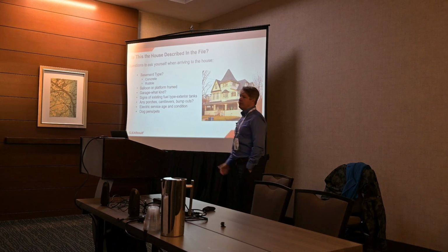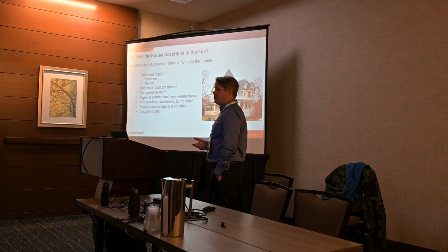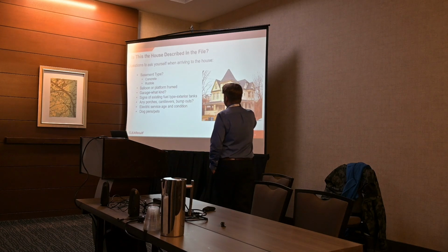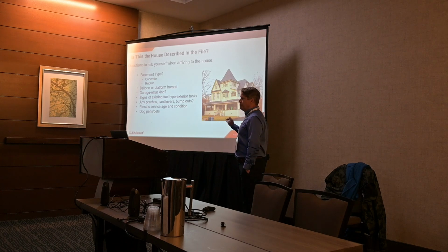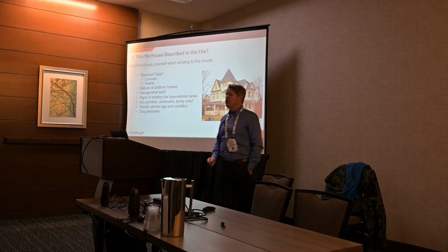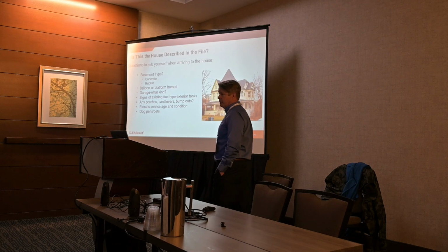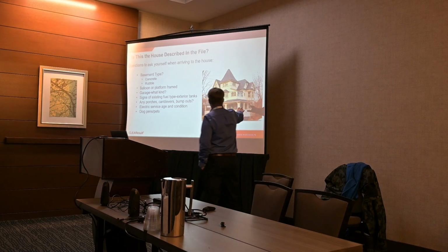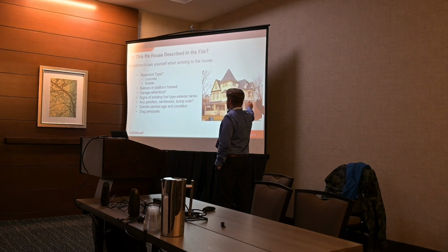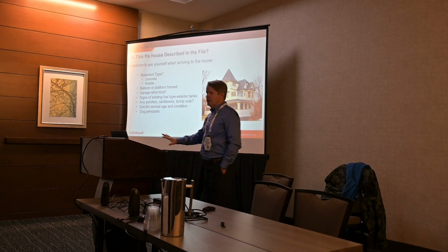Balloon or platform framed. Platform frames we can get tight pretty easily, right, with our typical air sealing measures. Balloon frames are a problem, especially if there's insulation in there, right? If we want a dense packed balloon frame to get the house tighter, and there's no insulation in there, we can do that successfully. If there is some insulation for some reason, it's harder, obviously, and sometimes not possible. Garage is important, right? If it's attached or underneath, then we have to think about air sealing to push that out of the conditioned space, right?